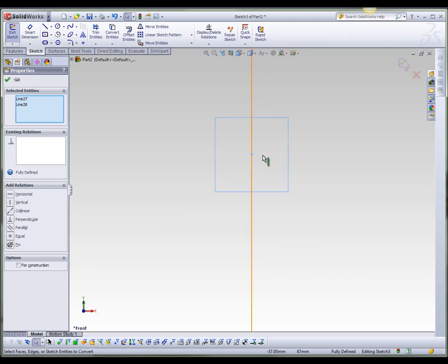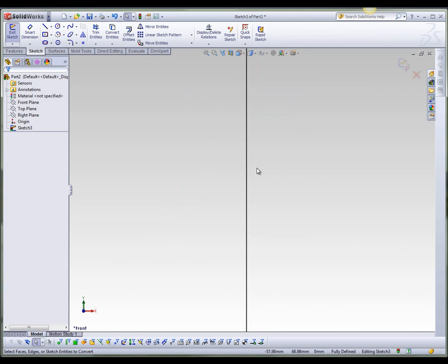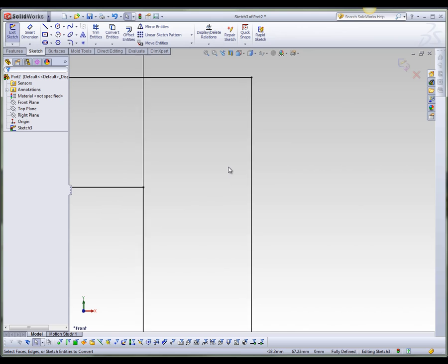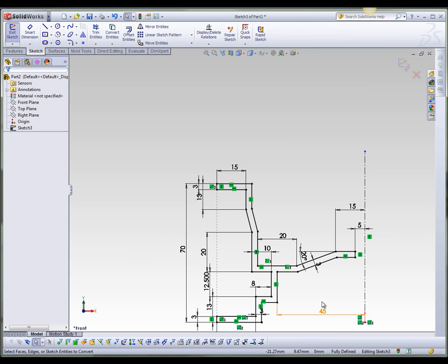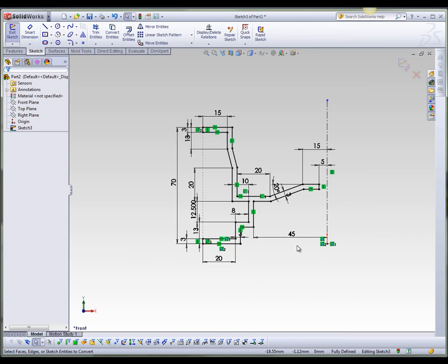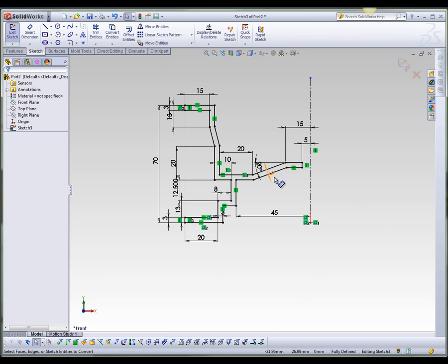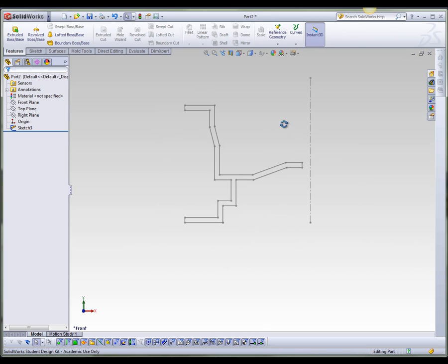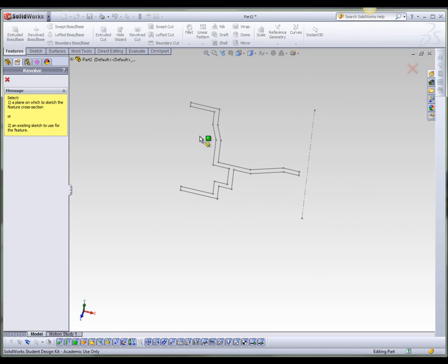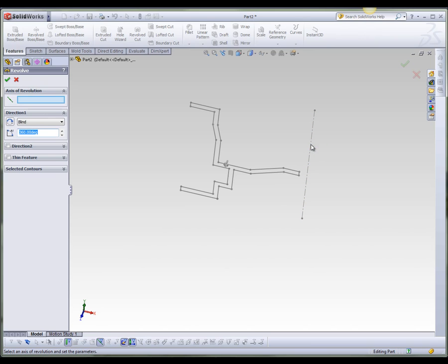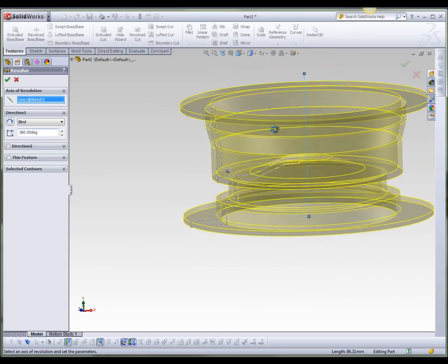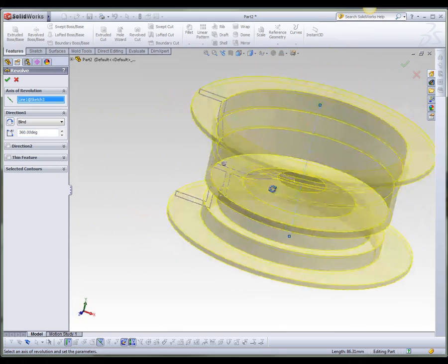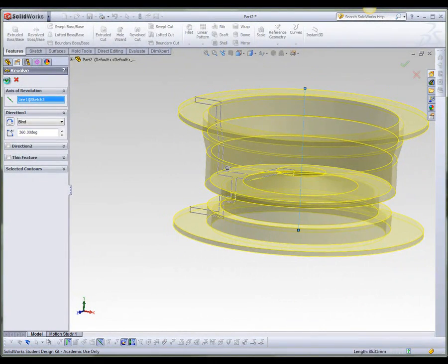This came about with the offset tool. I'll delete that. It tidies the sketch up. As you can see, it's still fully defined, but little things like that will prevent the sketch from being rotated properly. So let's complete the sketch. Now if I choose revolve, pick my centre line, and we get a preview of the component. Click the tick.